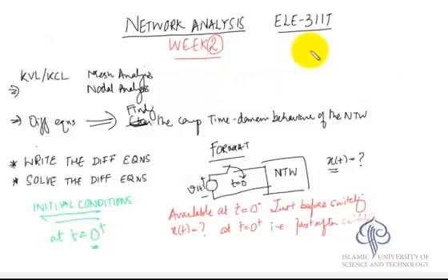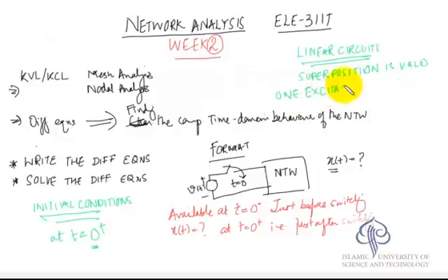The other important thing is that we should remember that we are talking about linear circuits. So the principle of superposition is valid. The advantage is that we can take one excitation at a time, see the response, and then add all the responses to all the excitations at the end. So throughout this course, we'll be talking only about linear circuits.